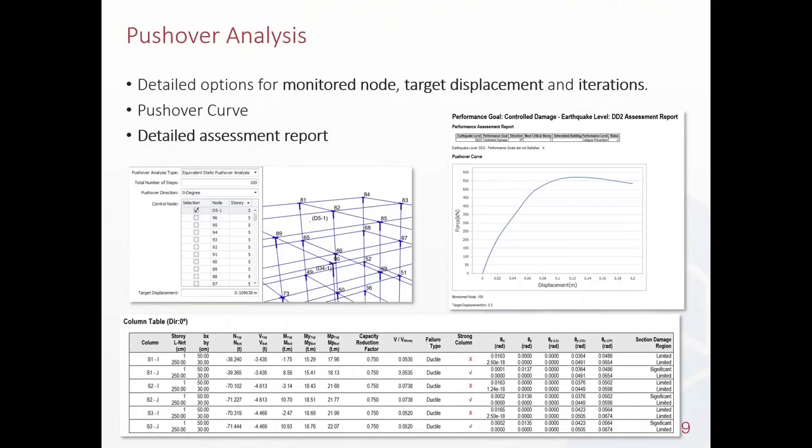For pushover analysis, we will look at different performance plots. You can look at any individual node, and we will create reports which check whether the structure satisfies the performance level you are targeting, whether it's immediate occupancy or life safety. Reports can be produced to see whether this meets those criteria.